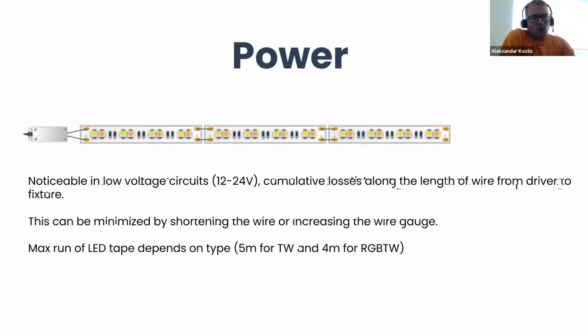So in order to properly design the wiring length against the LED tape location, we need to know the voltage drop of the specific wires we use and, based on the voltage loss index, calculate what is the optimal wire thickness for a specific length in the project.